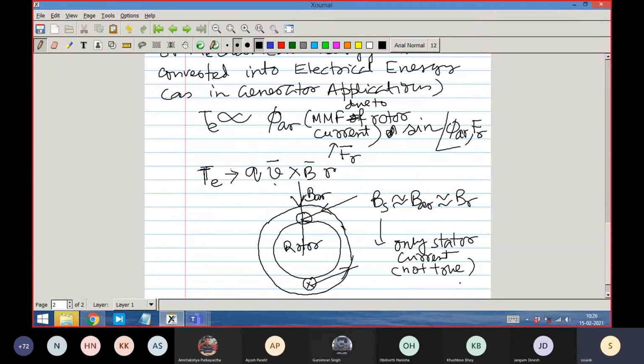So what I'm trying to say, again coming back to the point, is that the essential purpose of the machine is to create torque. And if I take conductor by conductor, this is the equation. This is the basic equation, the Lorentz law. But what is the torque in the case of an induction machine, or any machine which has a structure consisting not of one conductor but of many conductors? So then you understand what that is? What does your common sense say? Common sense should say that I have to add up the torques in each conductor, right?